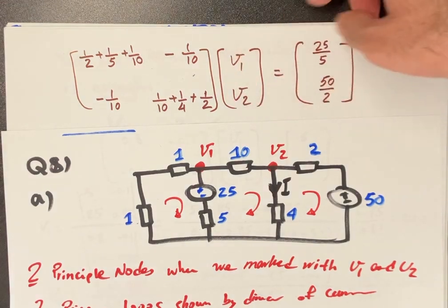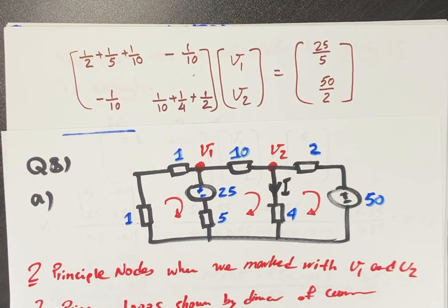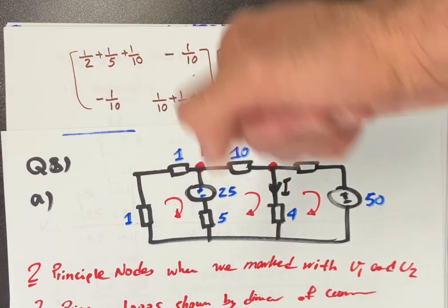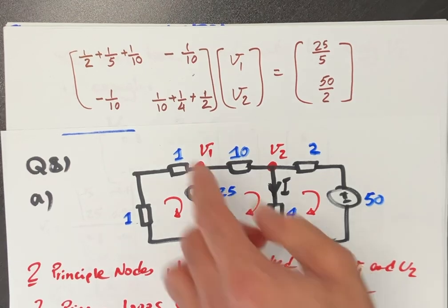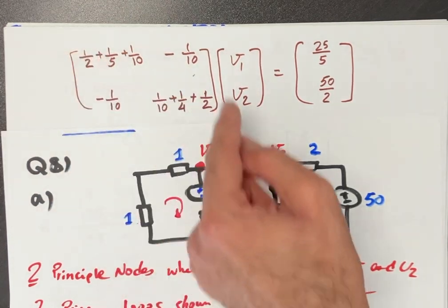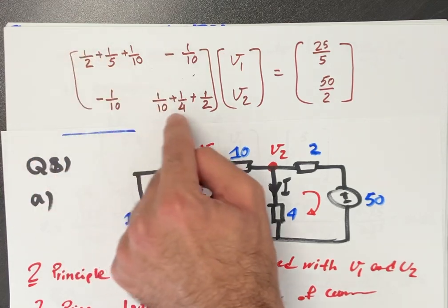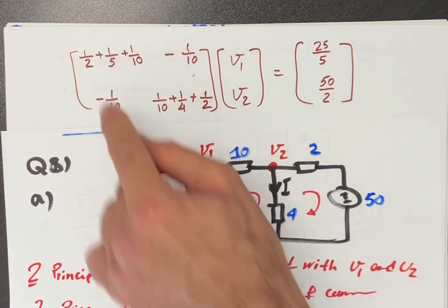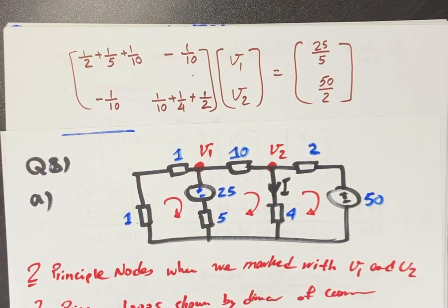These are my variables in the nodal method, and here I form the coefficient matrices, or conductance matrices actually. In this matrix we have diagonal and non-diagonal elements. For diagonal elements, like 1 1 or 2 2, for 1 1 you need to look at all the conductances connected to node 1.